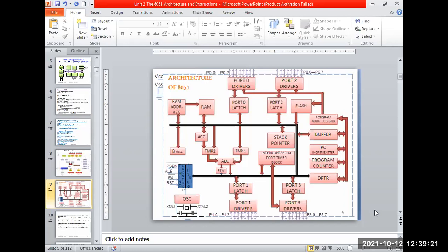Do you understand now? In this way, you have to write in the answer sheet. First of all, you have to write in one line how the resistors are connected to each other. You have to observe that 5 plus 3 is in parallel with 4, that is in series with 2, and that is in parallel with 2. Then you can solve bracket by bracket, and after that you can get the value.